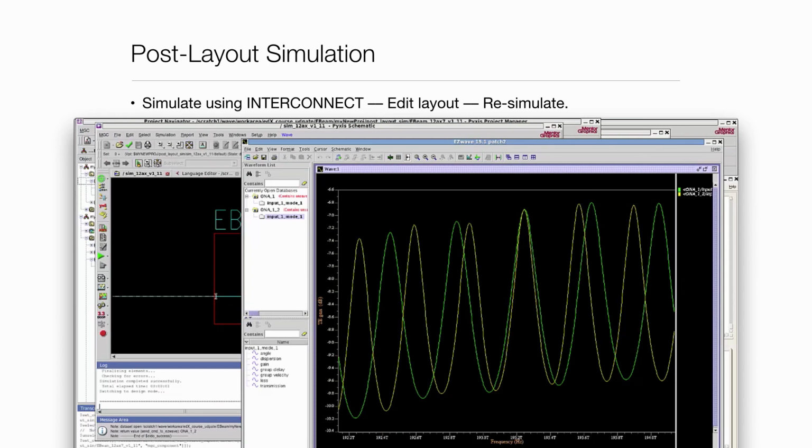We create a test bench for the design, configure the simulation, and Lumerical Interconnect is called to simulate the circuit. The simulation results are then viewed within Pixis. And that concludes the steps. With this approach, you'll know that your design is consistent, namely the schematic and circuit simulations match your layout. So go ahead and experiment with this methodology.